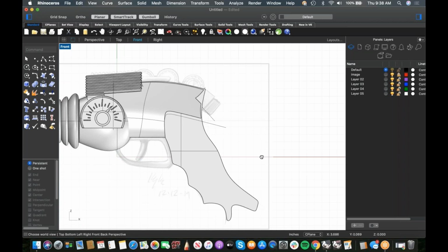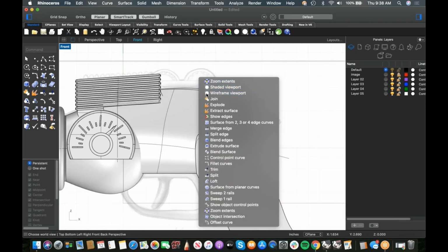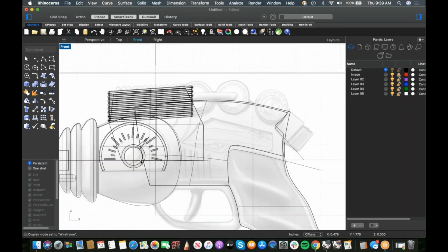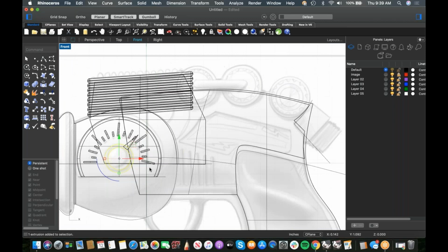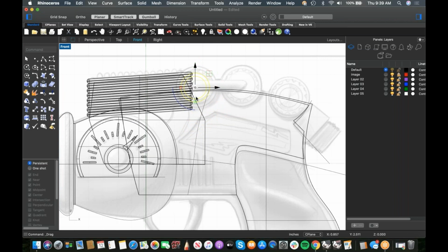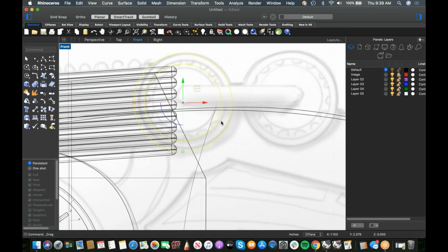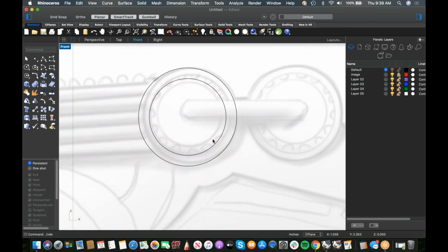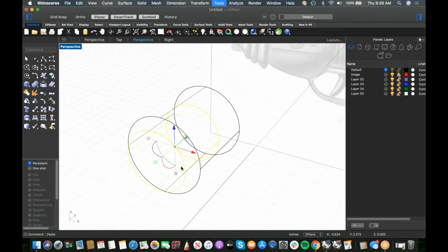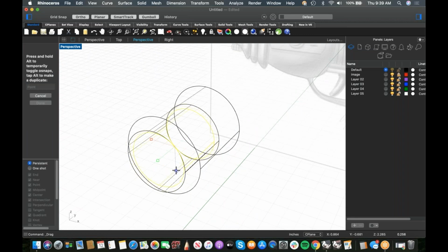Let's go ahead and make these details. This is a repeated detail, so we can make one and then just use it. And because I've already got the basis of that detail down here, I'm just going to steal it with an Alt-tap drag. And then I'm going to scale it up like that. And then I'm going to isolate that for now, so all we do is look at that. And it has a chamfer little step detail in here. Actually, it's not a chamfer, it's just another stacked cylinder. So let's go ahead and add that. Command C, Command V, Shift drag, and then let's stick it out a little bit like that.